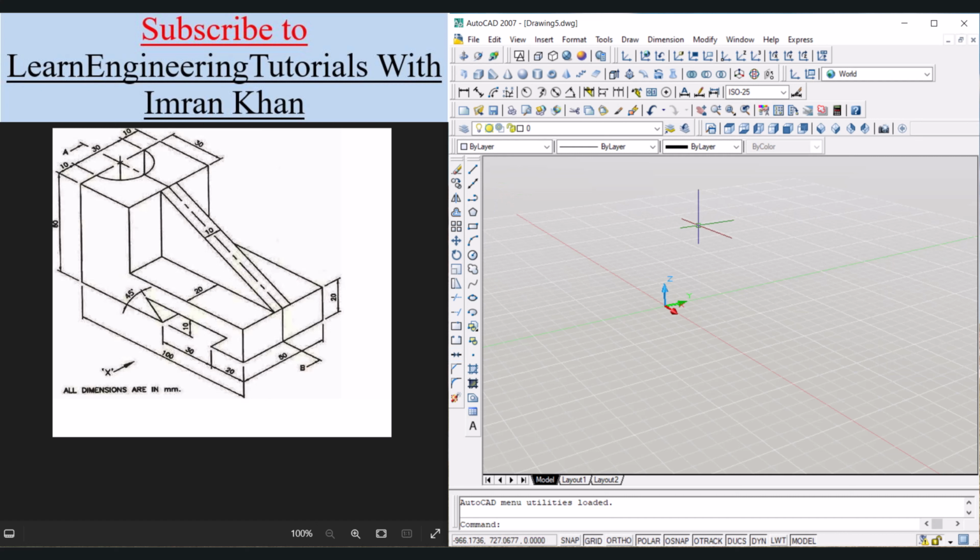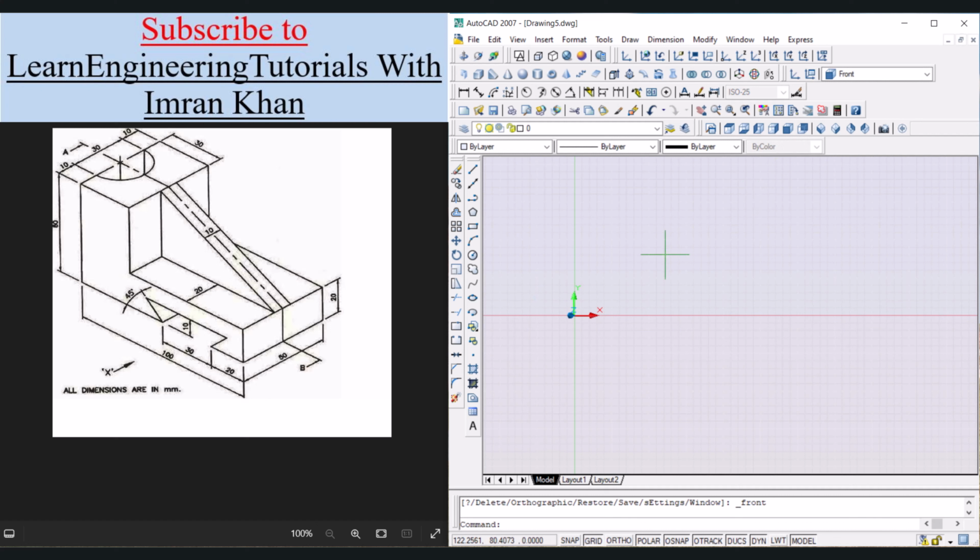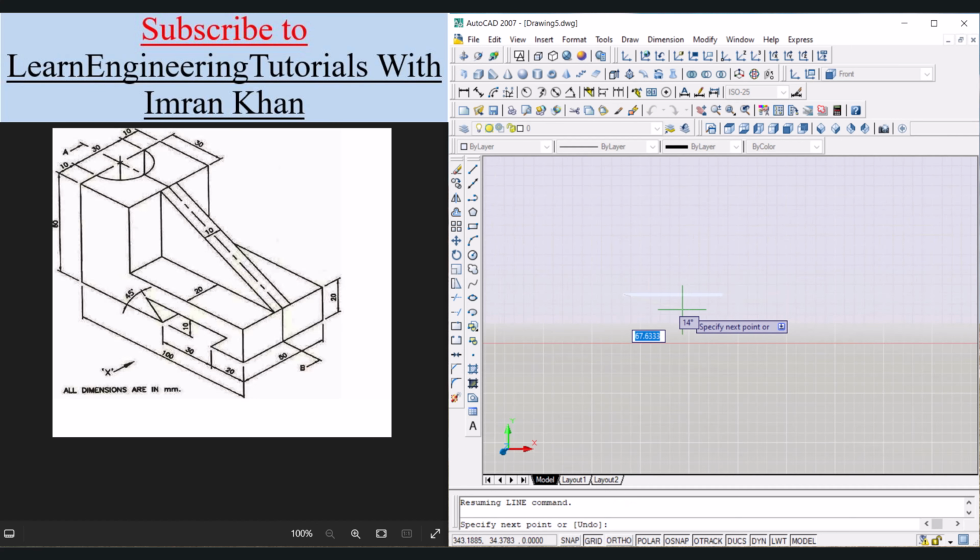Now first we have to go to the front view and we will draw this shape, right? So we will go to the front view, click on front view, let the line weight thickness be turned on. Now let's click on this line icon. We will start from this corner. Now in this direction we have the length of 100. Enter, zoom in.